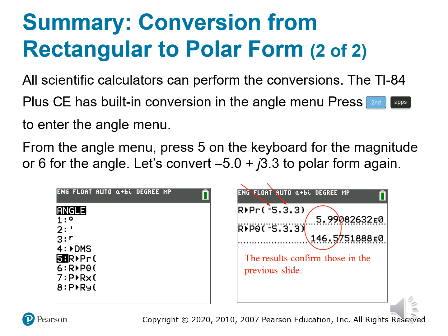And why does this matter for, let's say, RC circuits? If you remember, in an RC circuit, capacitive reactance introduces a phase shift. So when you're solving AC problems, converting impedance or current values to polar form makes it easier to multiply, divide, and understand those phase relationships. Instead of mapping every single triangle manually, a few calculator keystrokes lets you model that phasor voltage drop across the capacitor instantly. So this kind of thinking is efficient, clean, and analytically aware. It's exactly how we approach the math in the inductor podcast.